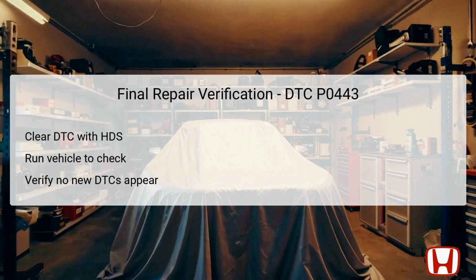Upon completing all appropriate repairs for DTC P0443, it is crucial to verify that the fix is successful. Start by clearing the diagnostic trouble code using the HDS. Following that, operate the vehicle under typical conditions to ensure that it functions properly without any reinstated issues.